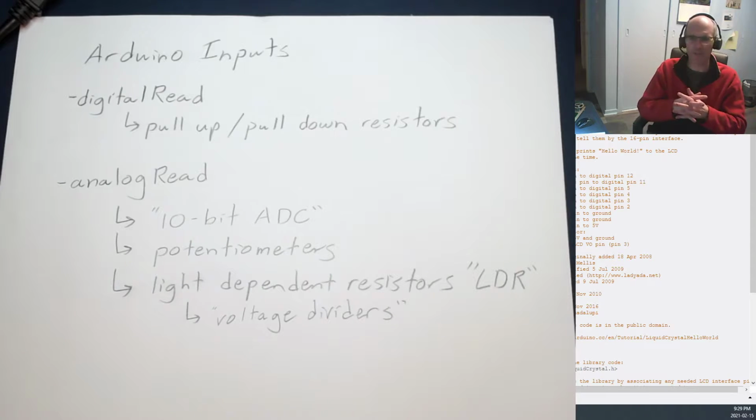Now, before I go too much further into this, I know that a few people in the class have been having trouble getting their LCD screens to work properly. If you've got it working in TinkerCAD and you've gone over your wiring a couple of times and you've taken a good close look at it, you've watched for that potentiometer in there where we gave it a little bit of a bend on one leg. Email me if you're not quite sure what I'm talking about with that. Then tell you what, bring it in next time you've got class with me on campus, and we'll find time to sit down and take a little bit of a look at it if you don't have it working just yet.